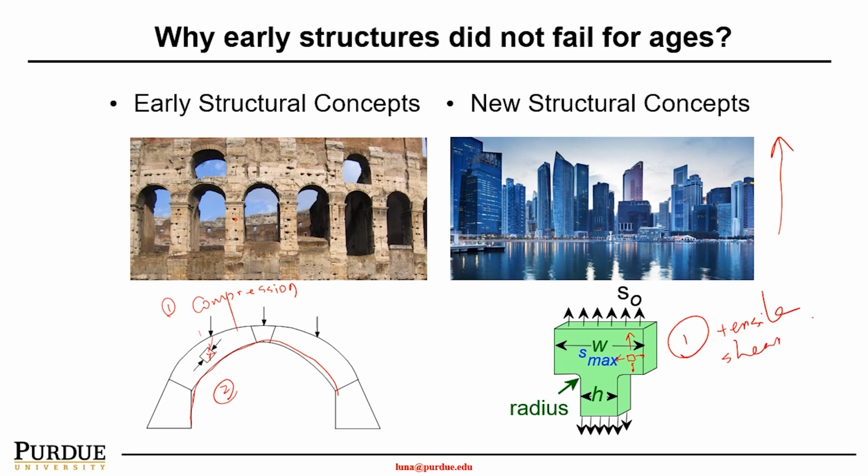shear. Number two, as can be seen, there is many complicated geometry which will lead to very sharp tips. In these corners or tips, the stress can be easily concentrated. This will create a very weak spot, or we call it the stress concentration. As a result, the stress can be magnified to orders of magnitude. That will lead to a very dangerous place for the materials to fail.